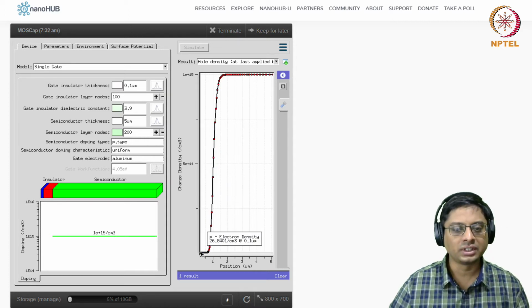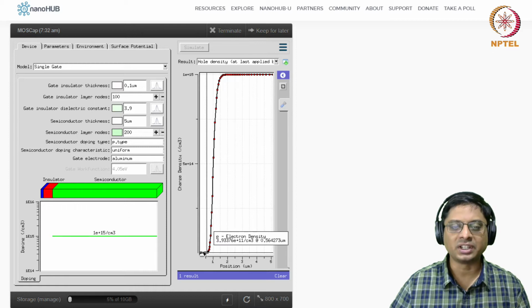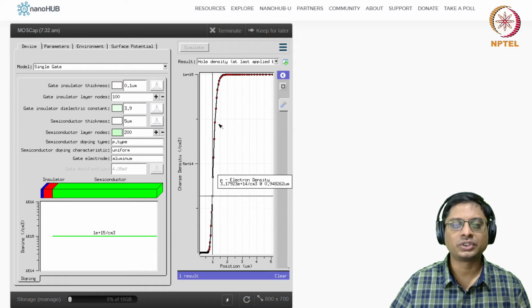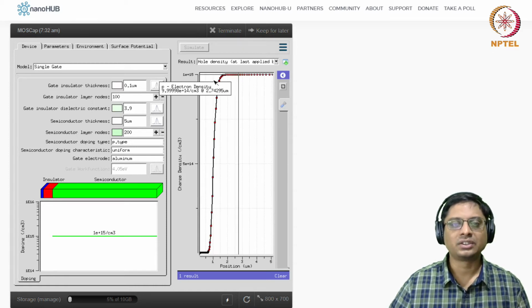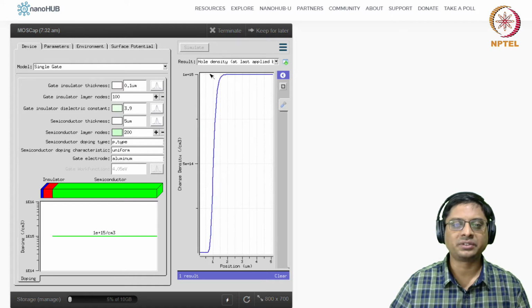The 0.1 micron is flat. So basically it is completely depleted here, and then the holes are increasing in this fashion, right? So we saw this. We defined a delta depletion this way. We made a rectangle, sorry. But essentially, yeah, minus 10 power 15 is what we were showing. So it's completely depleted, all right?